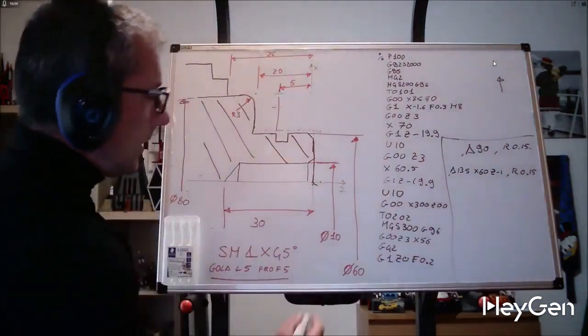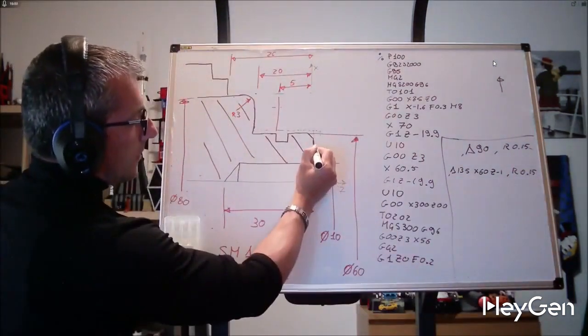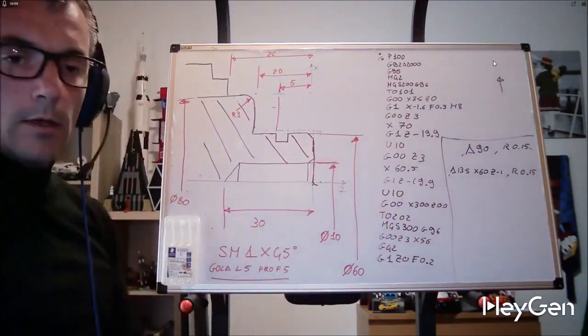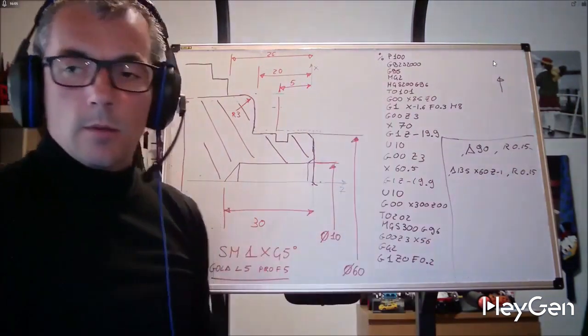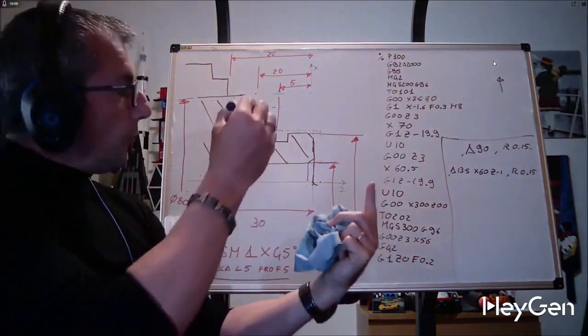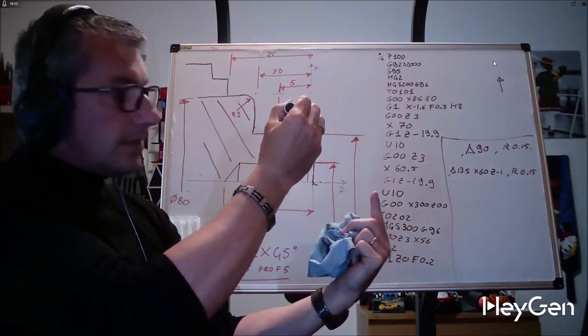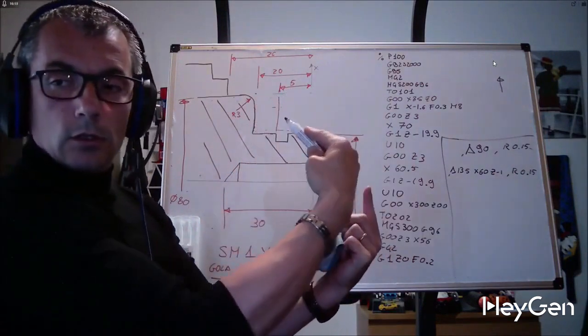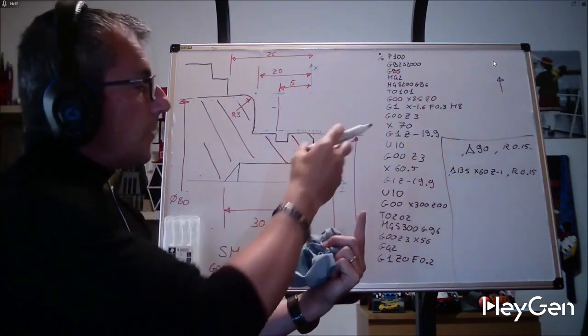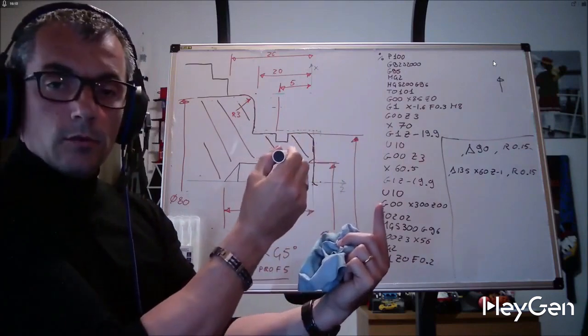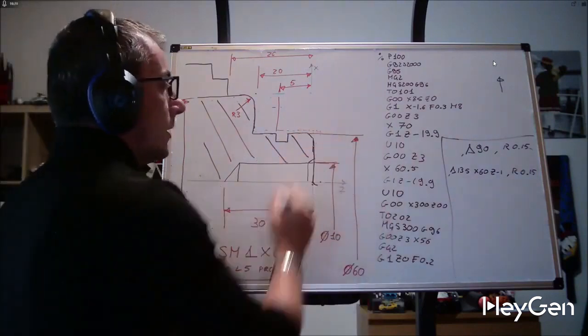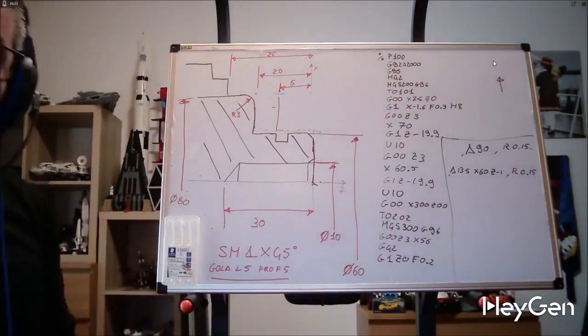I go to X56, Z0. I'm here, then I tell it to go up at 90 degrees. I give it some information: you stop at Z-1 X60, and you reach 135 degrees, which is 45, and in both cases, it finishes the trajectory with a 0.15.